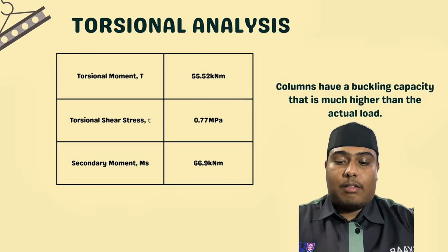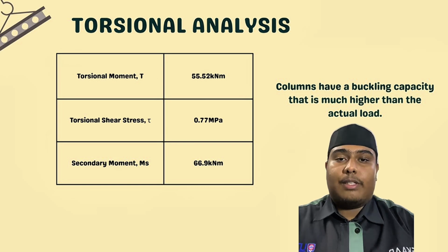Based on this result, the beam is able to resist the applied torsional effect and remains within the allowable design limits. In addition, the columns have a buckling capacity that is much higher than the actual applied load, which means the columns are structurally safe against buckling failure.